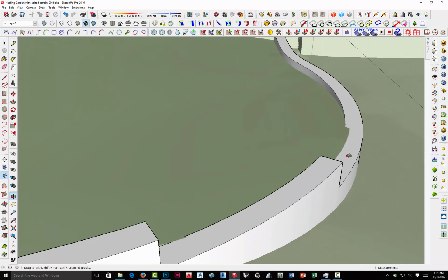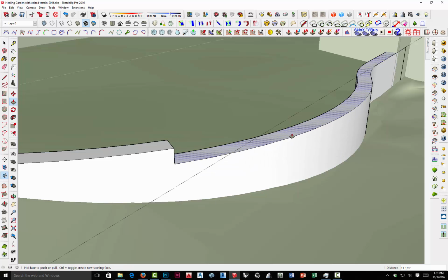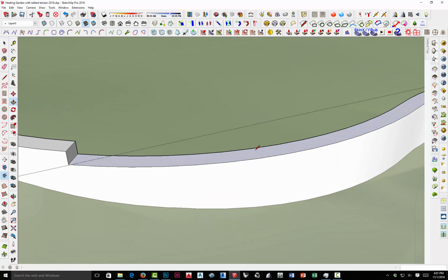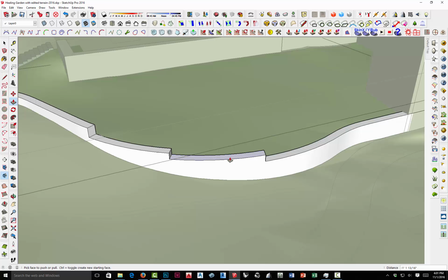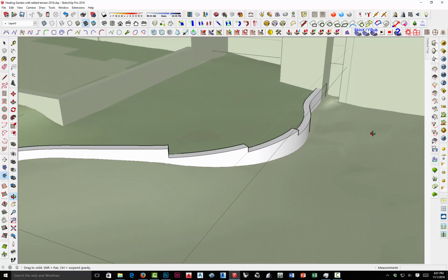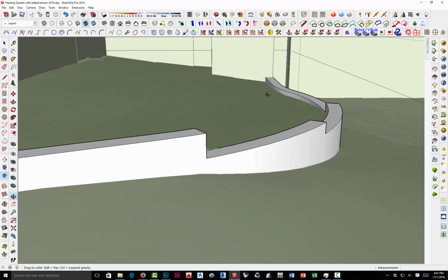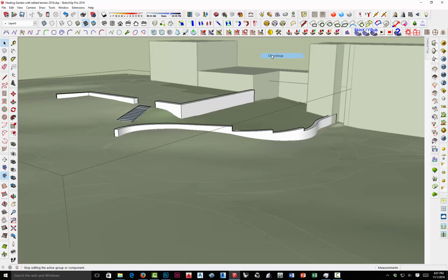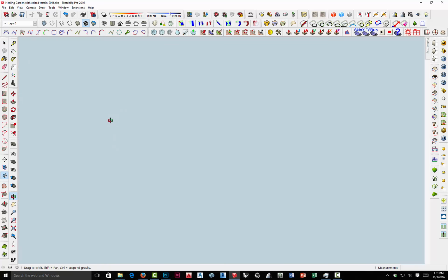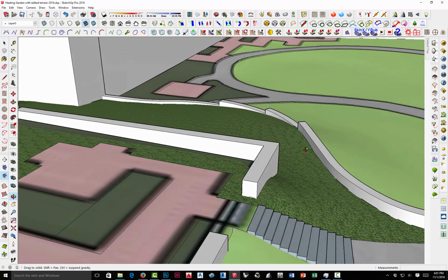Okay, so when you see yourself coming into the landform, that needs to stay up a little bit. Come over here, another edge, push pull. And actually, just looking at that, that's pretty even the rest of the way, so I probably wouldn't bring that down anymore. So now that gives me this kind of stair-stepped wall that when you look at it on the inside, the landform is pretty much up there.